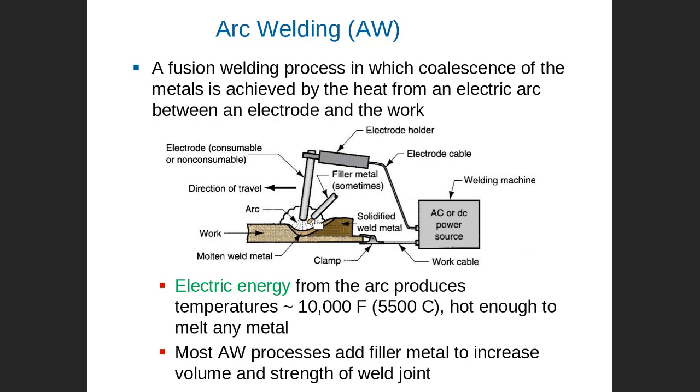This is what we call arc welding. An arc will be created. This discharge between the electrode and workpiece is the arc. And then electrical energy becomes thermal energy. Temperature will increase up to melting the workpiece material, in the welding zone only, not all the workpiece material, definitely. Then you get a liquid mix, and then the weld.